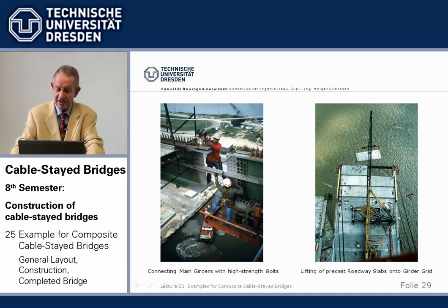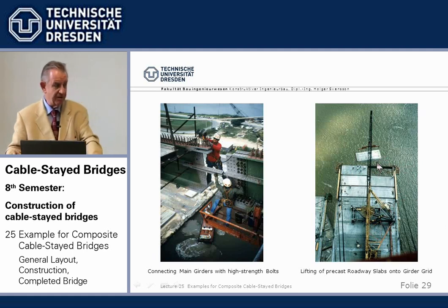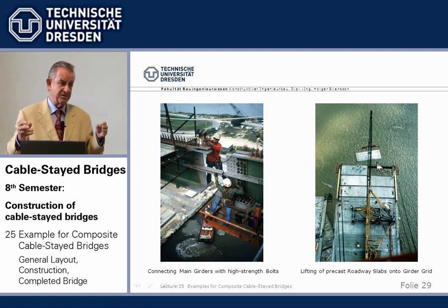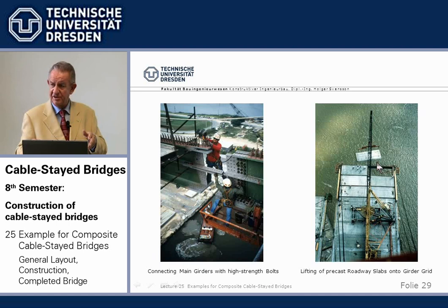Now, after the steel grid is installed, we then transport the deck up with the same derricks. We had the basic consideration: do we want cast in place or precast? We had offered both in our tender documents, but the contractor decided he wanted to do it, as you say, on site, piecemeal in small pieces, and then accept the joints, which are of course the shortcoming. On the other hand, shrinkage and creep is less. So this is a good method.